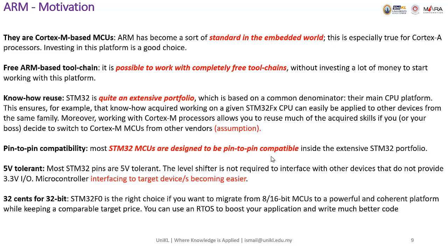You need some sort of converter to convert from low-voltage logic to high-voltage logic, TTL at 5 volts, to drive something that is TTL, for example. And when you read data from TTL, you need to drop that voltage to low-power TTL or 3.3 volts. But the STM32 has designed some of their pins to be compatible, or 5-volt tolerant.